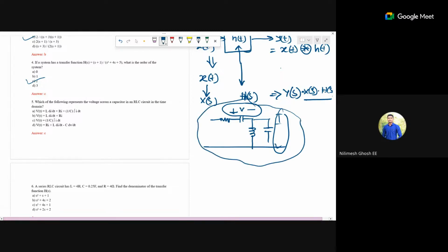And if you don't go to this one, you just have to do the pole-zero diagram of this one. This will have two poles in the left of the S plane. The poles location will be -4 plus minus root over 16 minus 4, something here. If this is the S plane, with sigma and j omega axes. You guys know now what poles and zeros are. Yes, sir, we know.